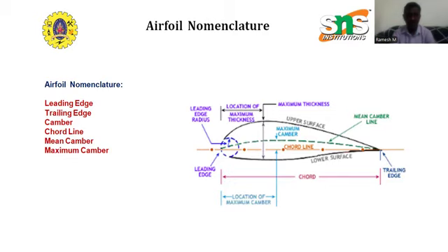And the cambered airfoil is an airfoil that has a curved shape, resulting in a difference in the curvature between its upper and lower surfaces. So lift generation varies with respect to the symmetric airfoil. Even at zero angle of attack, due to the camber, it produces lift. There is some amount of lift produced in a cambered airfoil. Camber can be optimized for specific flight conditions to enhance the lift and reduce the drag. NACA 2412 is a commonly used cambered airfoil with 2% camber and 12% thickness.